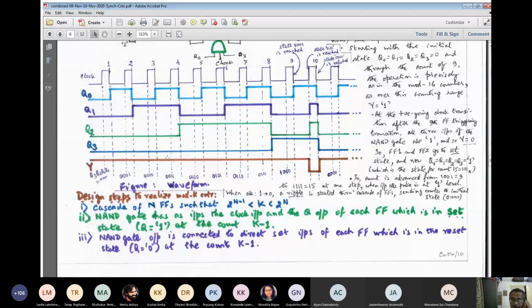Probably for some particular design or particular situation, it may be required. But for the time being, I can see that only the 0 to 1 transition and the 1 to 0 transition should be clearly defined and fed to the flip-flop input. There is not much requirement of keeping the clock signal with a particular duty cycle, so far as I know. If I come to have any more knowledge, I'll definitely share it with you.